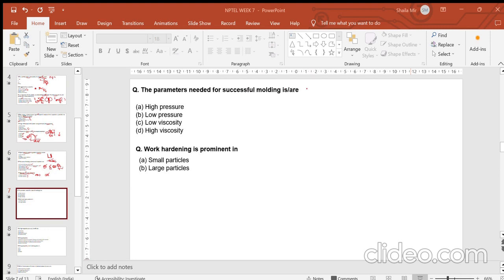You have simplified the equation and now it is 42.3 under root of the diameter of your mill minus the diameter of your ball. So you can write it as small d. This is the relationship between the critical speed and the diameter, a simplified equation when you just have to calculate the difference between the diameter and critical speed. This is very important for competitive exams. You remember the equation and then you can just plug in the diameter values.